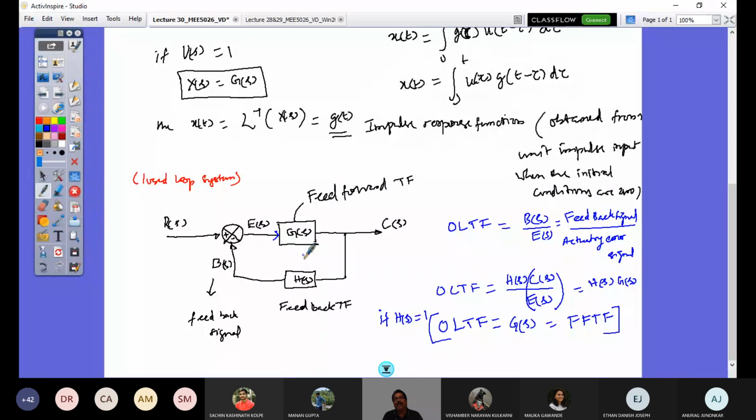So to attain that, you will always take a feedback to compare. So that is what is happening. So if this feedback signal and your input difference is 0, then the output has reached the steady state. If it is not so, then there will be a correction that will keep coming. So I will look at my output. Is it in accordance with my given input or not? To see that, I will take a feedback, and that system is what is called a closed loop system, right? Is that clear?